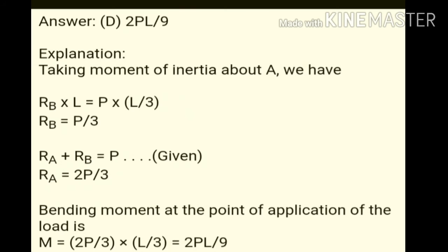So from this, now what is the bending moment at point P? How do we calculate the bending moment? You can calculate from the right hand or left hand. So at point P, if you calculate from the left hand, there is only one reaction force you can find from the left side, that is equal to 2P by 3 at a distance of L by 3.